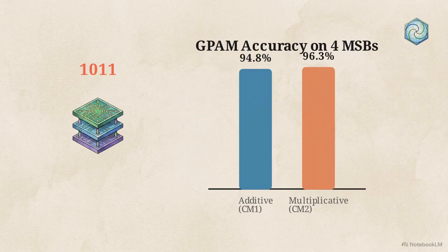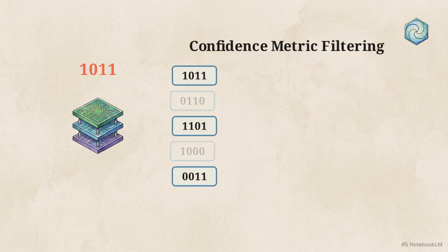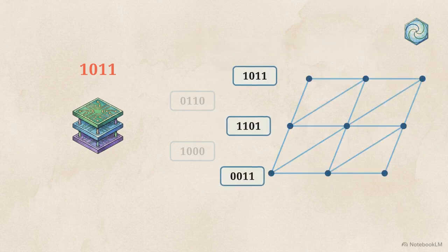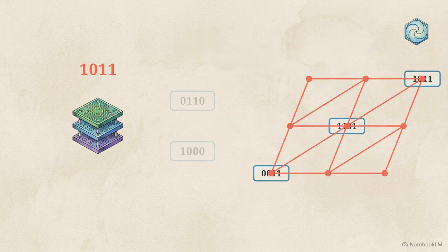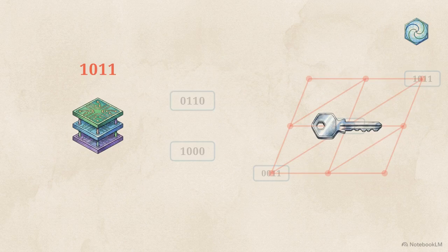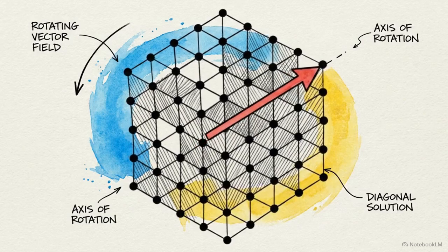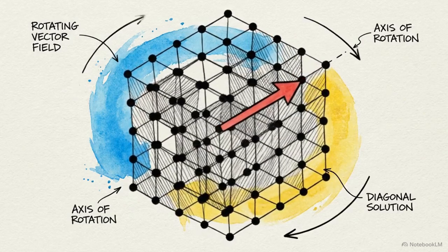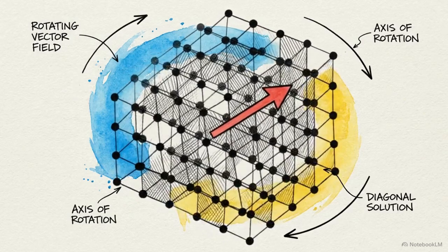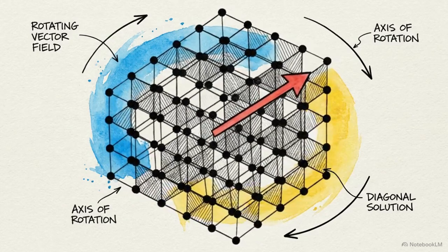multiplicative masking. The attacker extracts these highly confident partial predictions and feeds them directly as inputs into a standard mathematical lattice attack. The deep learning model extracts the signal from the physical hardware, and the geometric mathematics of the lattice attack reconstructs the missing data. Together, they compromise the full secret key using just a few thousand traces.